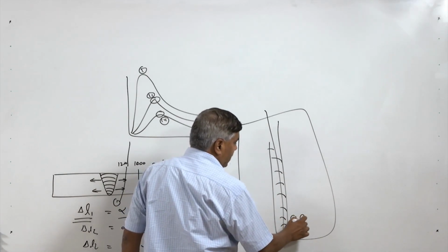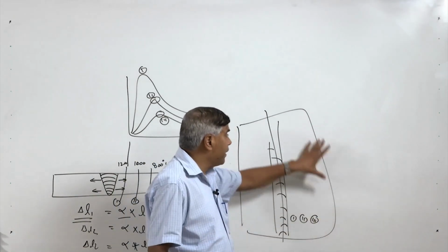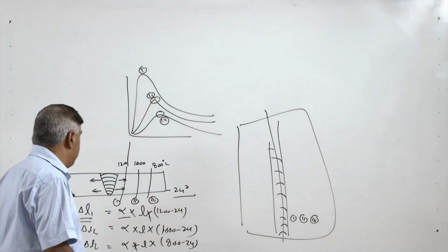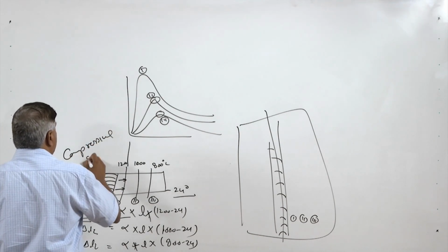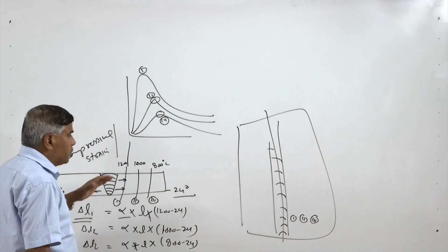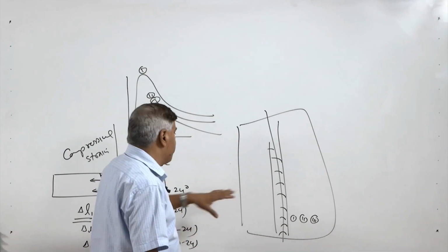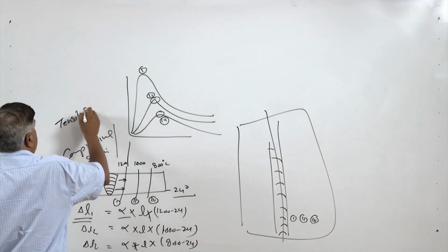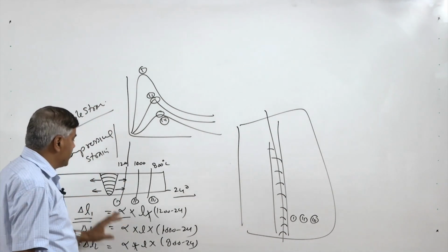Like one area, second area, third area, all these zones are being heated to different temperatures. But since these are an integral part of the entire plate, their expansion will first be restricted, so they will feel compressive strain during the heating because their expansion has been restricted. Once things have cooled, they should shrink, but that shrinkage is also restricted, so during the cooling they feel tensile strain. Initially they experience compressive strain due to the heating and then they experience tensile strain.